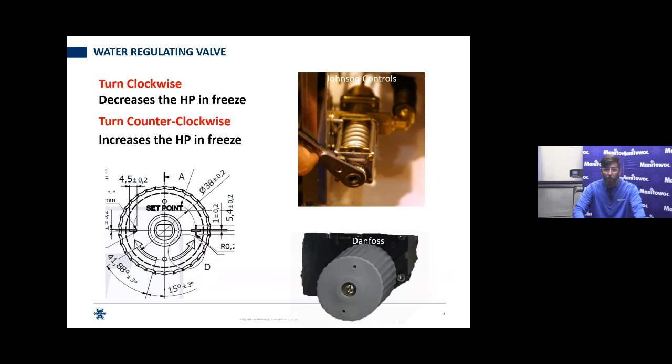Big thing, if you don't remember this at the end of the day, one of the things that we teach in the factory school is have that gauge on there, turn that valve just slightly. If you were trying to go up and you went down, well, sorry to tell you, you're going the wrong way. Let's turn that valve the other way and get our head pressure set. Key with this is remembering that this is what we utilize, whether it's a hand valve or a special wrench that needs to be turned to adjust that head pressure.